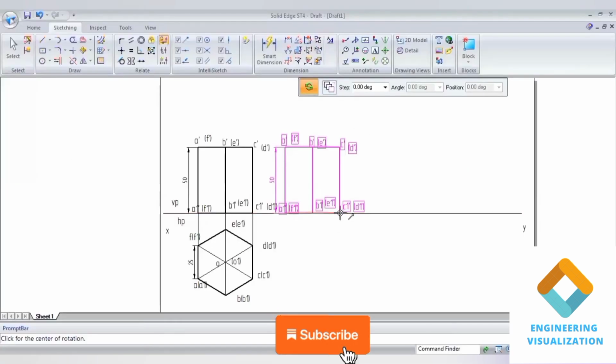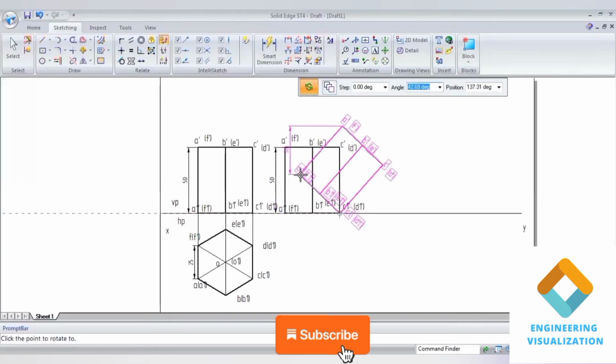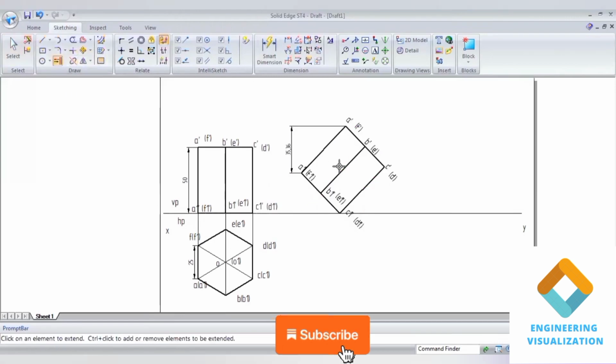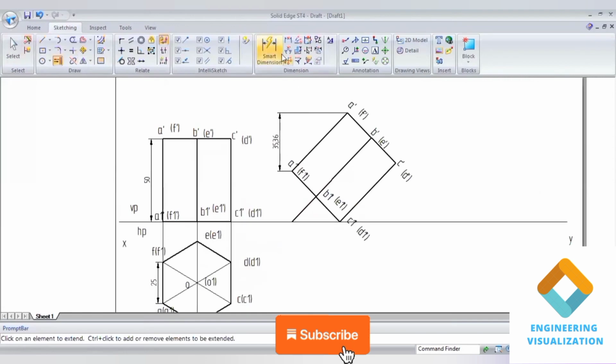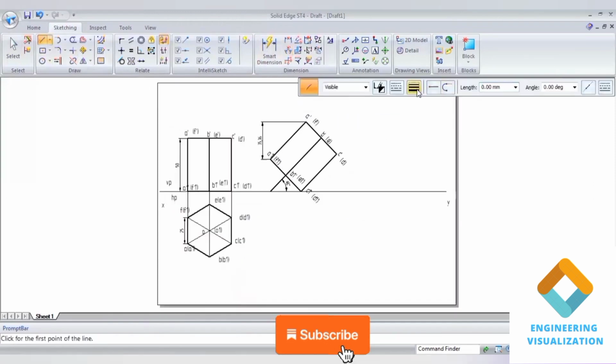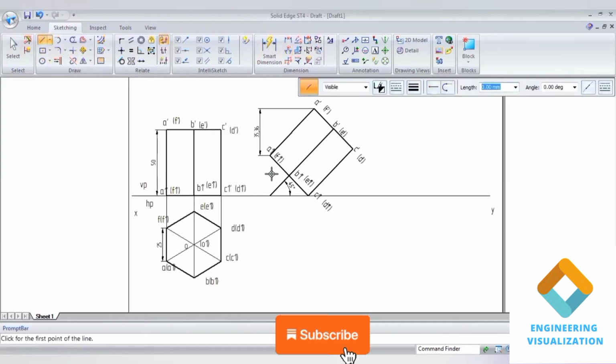The inclination is 45 degrees. So incline 45, and it has been inclined. Now extend the axis, find the angle, and project downward to complete the second position top view.